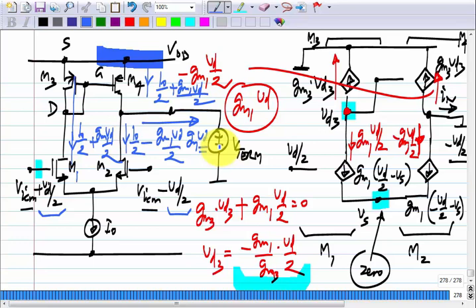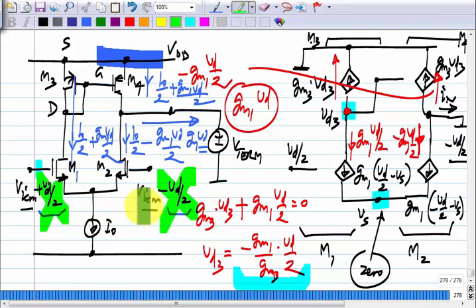So, now what else is there to be found? We have to find the output resistance. That thing is the same for Thevenin and Norton. Essentially, what we have to do is, we do not have any incremental input. We null the incremental input. The operating point will remain exactly the same, and we find the resistance looking back that way.